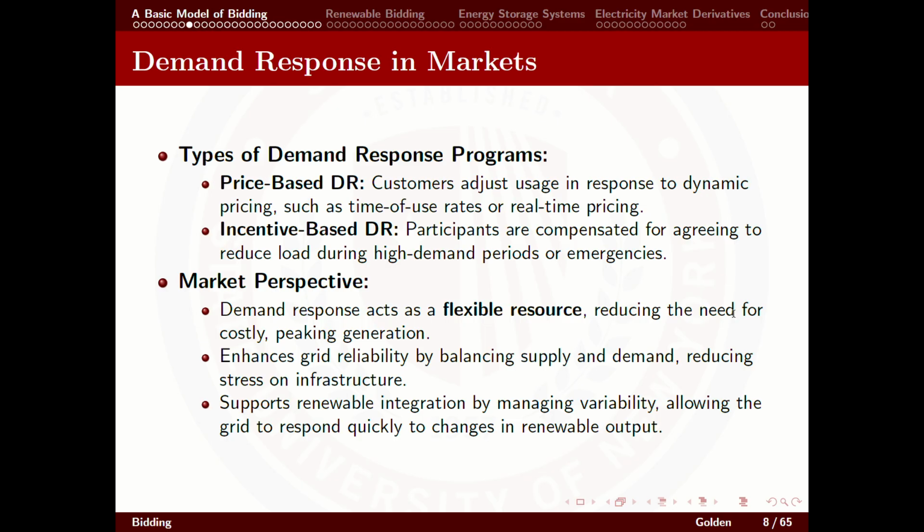So one thing I'll mention is that one of the flaws of demand response markets, and something we're working on right now, is it relies on you to understand how you're reducing power from your peak. So it relies on you to reduce power, but it's not always clear what your peak is. Normally you're asked to provide some sample dates that demonstrate how much power you're normally using. Some businesses have incentives to overestimate and have used too much power then. So during a real demand response event, it will look like they're cutting back when actually they're just using normal power.